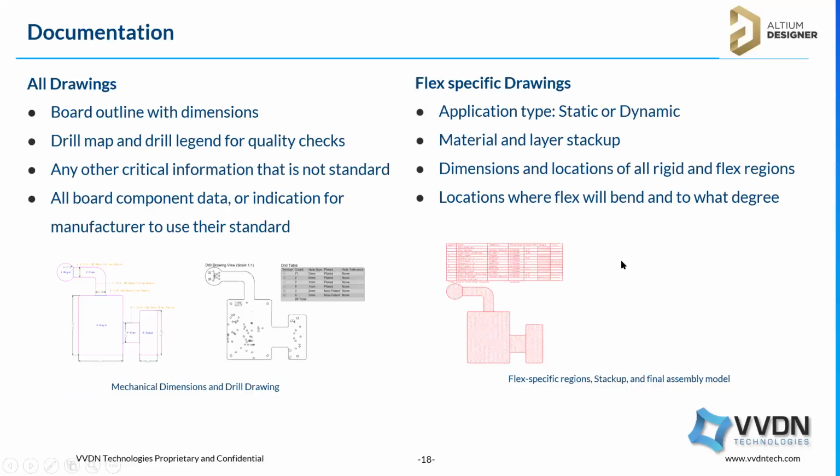Documentation, so we can create fabrication documentation for this. For all drawings, like board outline with dimension, drill map, drill legend for quality checks, then critical information we can provide, and all board component data or indication for manufacturing to use their standard. So those things we can provide.